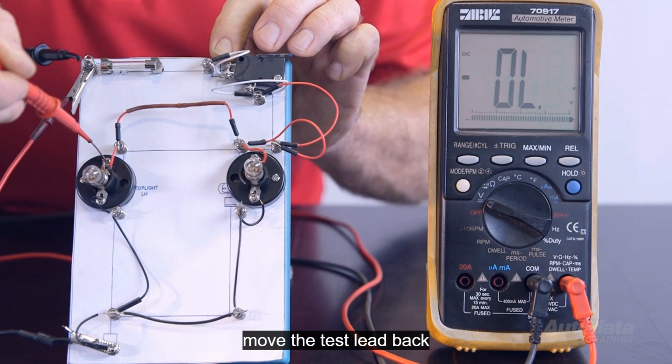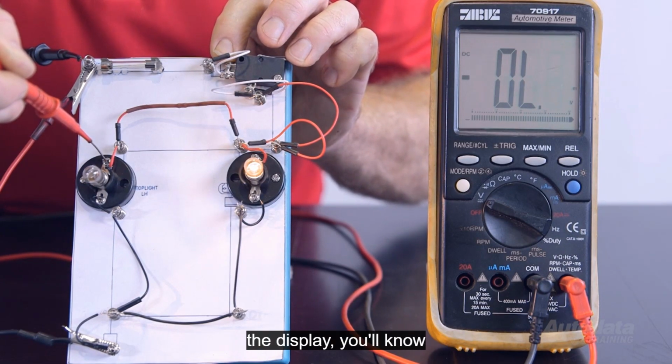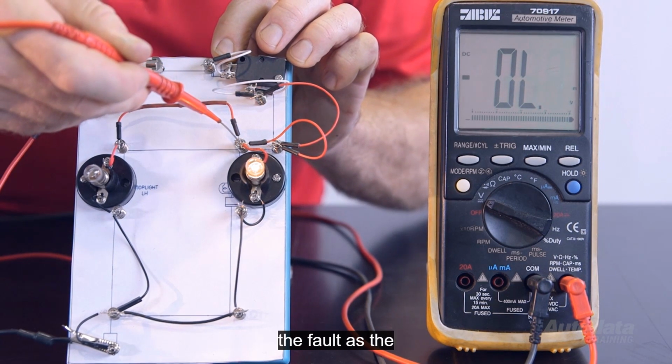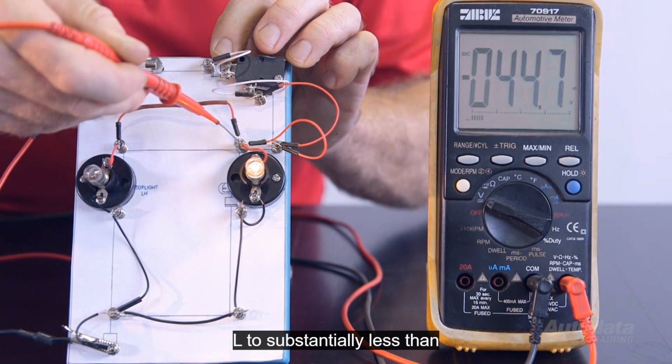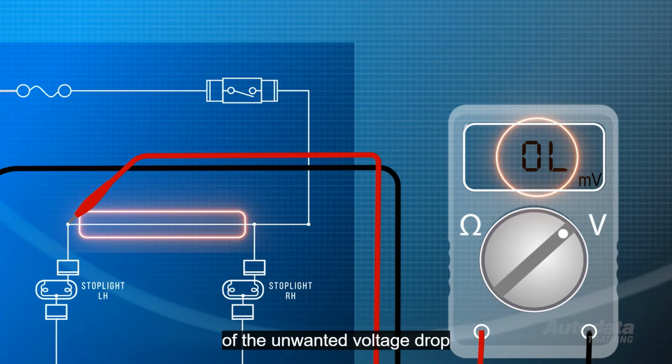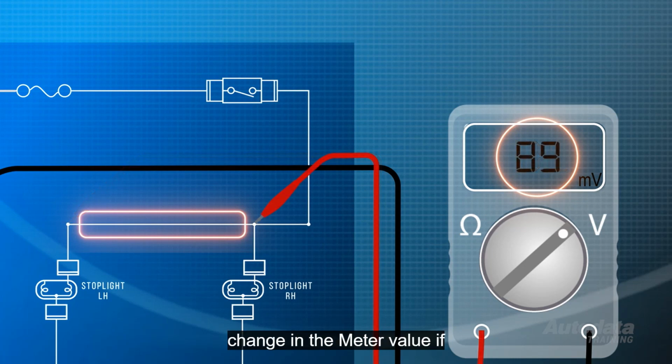Move the test lead back toward the battery while watching the display. You'll know when you've passed the location of the fault as the meter reading changes from OL to substantially less than 500 millivolts. The source of the unwanted voltage drop can be identified by this change in the meter value.